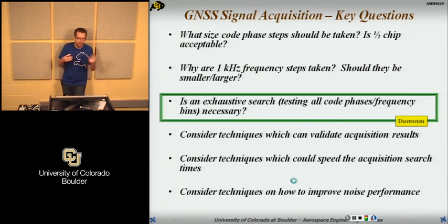But let's say we know roughly where we're at, and we know roughly what time it is. And we managed to find one PRN signal, and we tracked that for a little while, so we know what time it is pretty close. Then we can actually use the almanac that we assume we already have to predict where the other satellites are going to be, and from that predict whatever that Doppler is going to be. So the more information we have, the more we can reduce the problem.